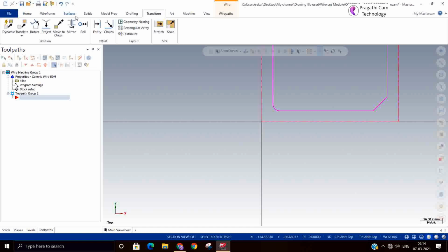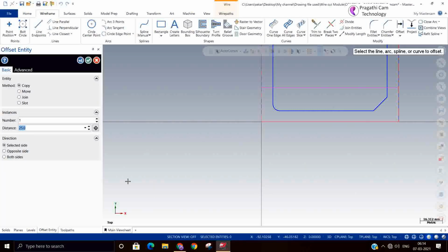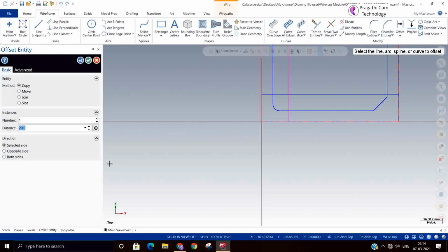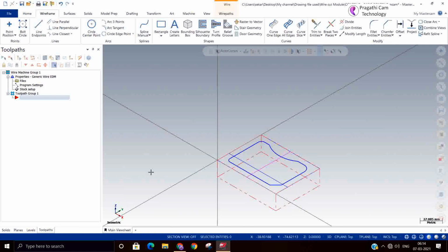So it is very easy for the operator to position your workpiece and start working. So in order to maintain this exact stock position, means thread position, I just offset this and make that thread point and cut point in the right place.